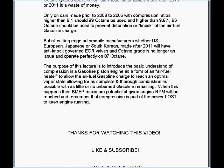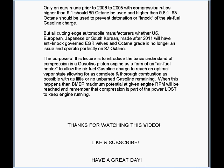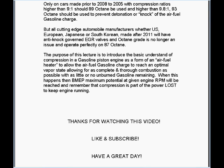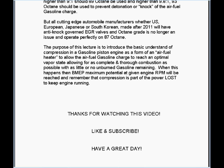Only on cars made prior to 2008 to 2005 with compression ratios higher than 9 to 1 should 89 octane be used, and higher than 9.8 to 1, 93 octane should be used to prevent detonation or knock of the air-fuel gasoline charge. But all cutting-edge automobile manufacturers, whether U.S., European, Japanese, or South Korean, made after 2011, will have anti-knock governed EGR valves, and octane grade is no longer an issue and they operate perfectly on 86 and 87 octane.